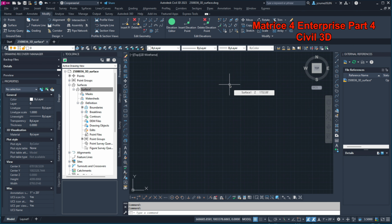Okay, let's move into the final stretch here. We've built the ortho, we've built the DSM, we've gone through Global Mapper, we've created the break lines, the limit line, the hide line, and we've exported those out. Now we're into Civil 3D. So we create the surface, and that's from a template, the standard template that we have set up.